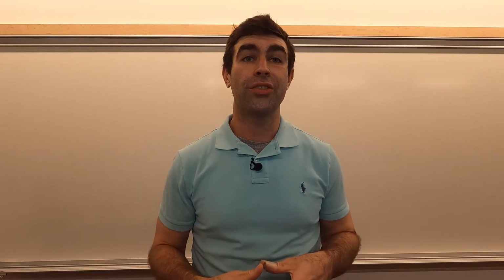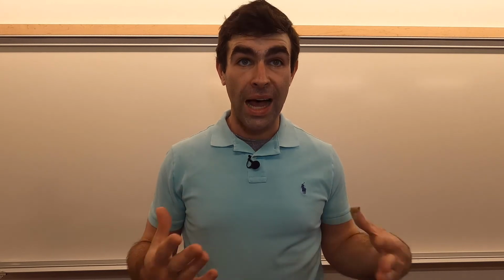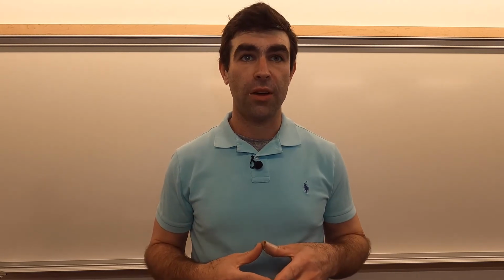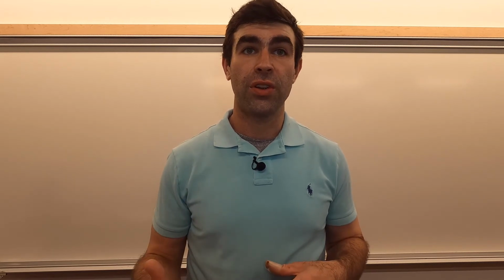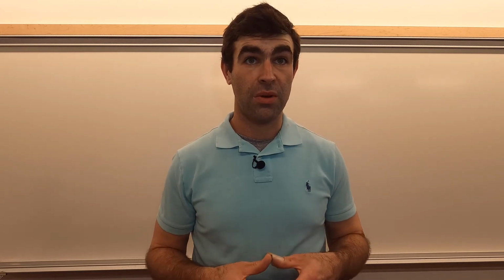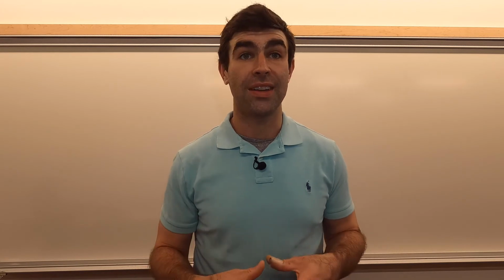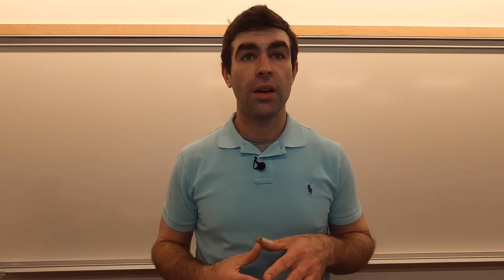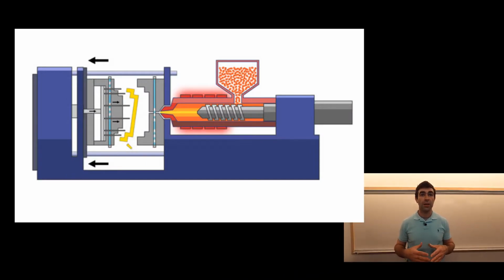So let's talk about injection molding. This is a hugely popular process that a lot of commodities are made out of. It's a very high volume process. The machinery and the dies are very expensive, so they typically use this for big production runs when they have to make thousands of something, similar to die casting. In this process, a measured amount of liquid plastic is going to be forced into the die. The die is usually 2 pieces.